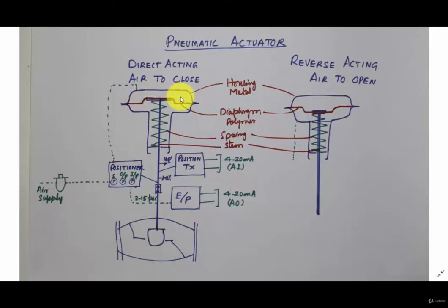When air pressure is applied on the diaphragm, it develops force and pushes the piston stem down against the spring force.